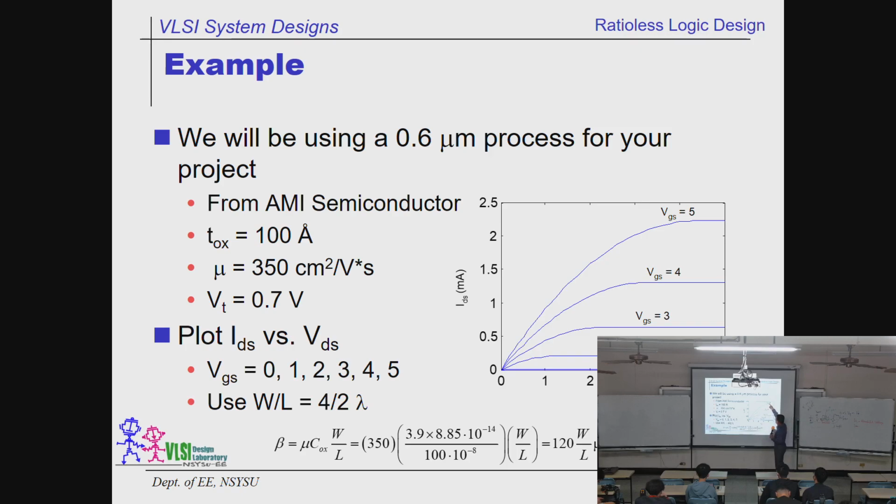You can see this one. For every blue curve, you find there is a special point. On the left-hand side, you will see the curve like this. It's linear, or almost linear. This is the resistor behavior. At a certain point, the line becomes flat. It becomes a fixed current, because this is current. That means no matter how VDS is increased, at a certain point, the current is fixed.